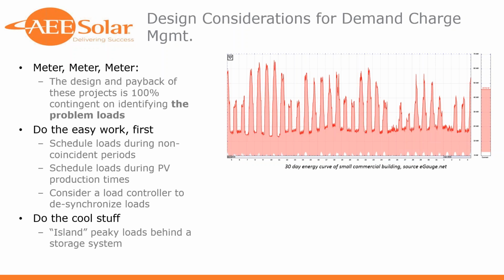which load is driving that peak kW number. It's not going to tell you at what time of the day. For that, you're going to have to get meter level data, which can be provided from a lot of the forward-thinking utilities out there. But you're going to need to get down to the sub-panel and sometimes circuit level to figure out if this is something you can address. The design and the paybacks of these projects is 100% contingent on identifying the problem loads.